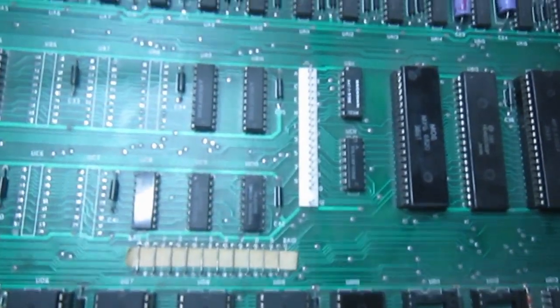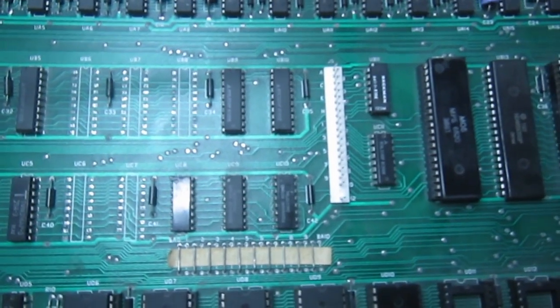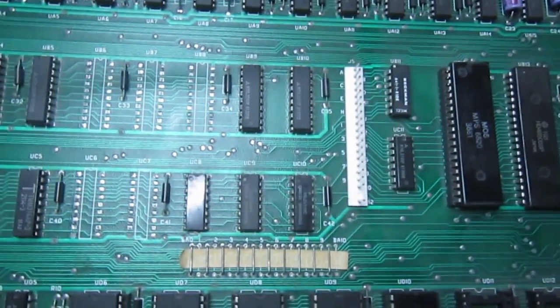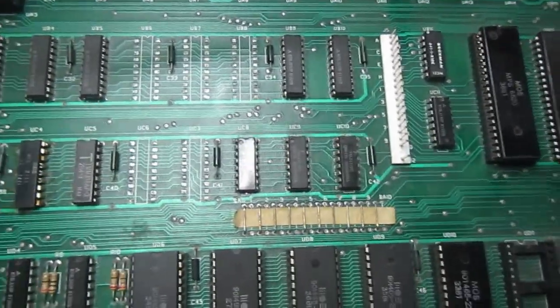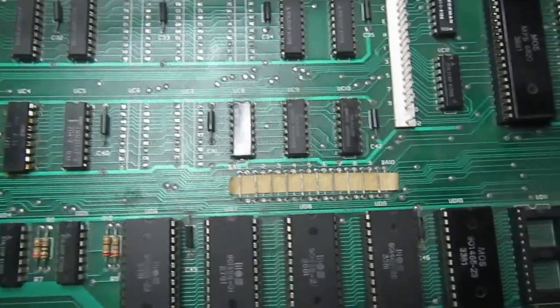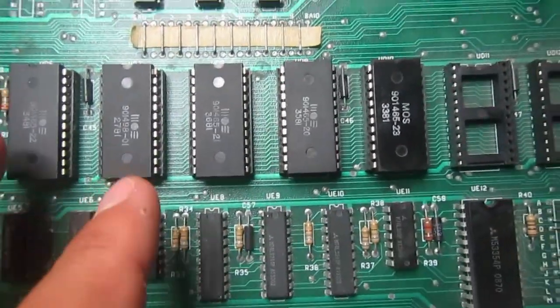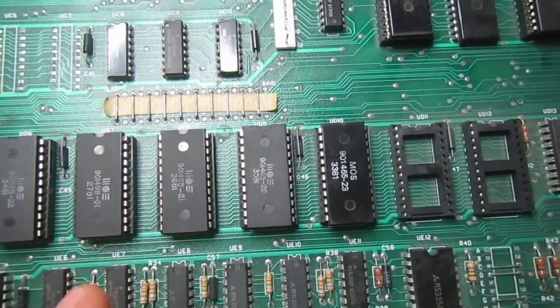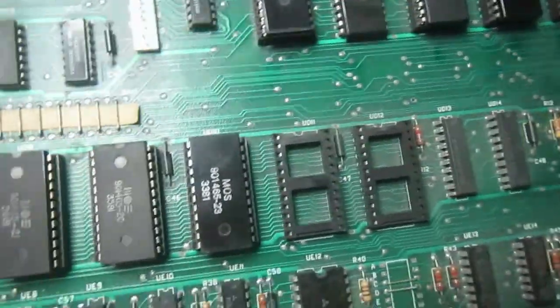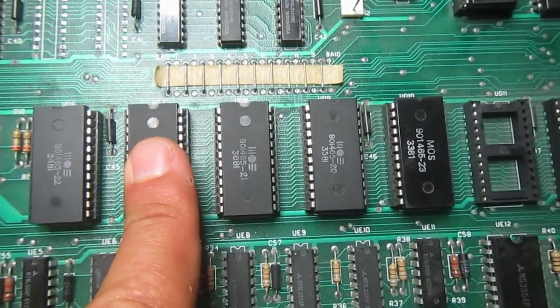And the composite signal is not used at the moment. That would be useful for the 9 inches CRT that has scan frequencies compatible with NTSC or PAL, well, more or less, but at this moment it works well enough with this configuration. So another option, if you don't have access to a monitor that can sync to about 20 kHz horizontal sync, would be to substitute the editor ROM.